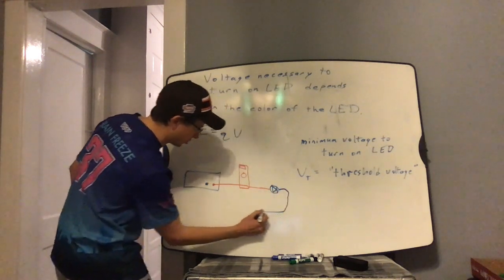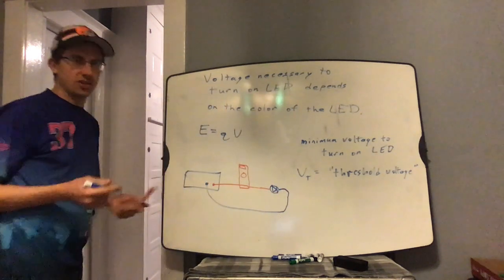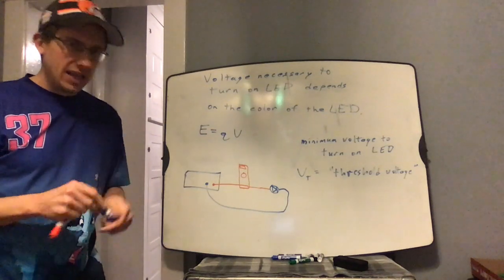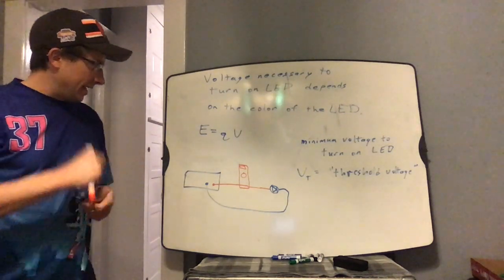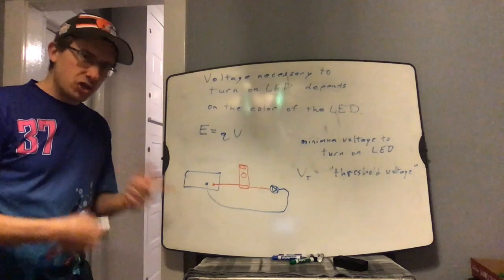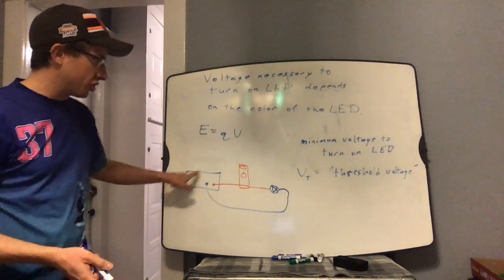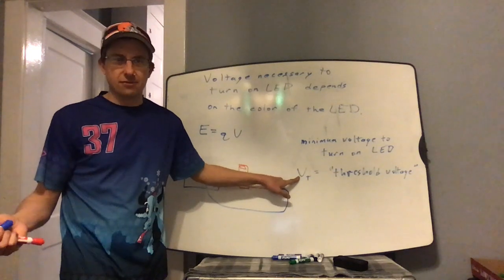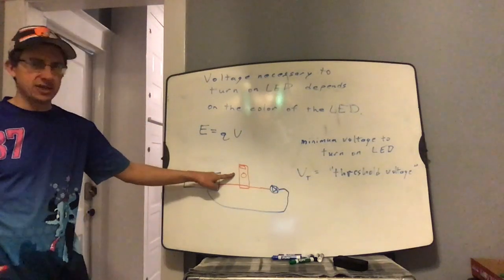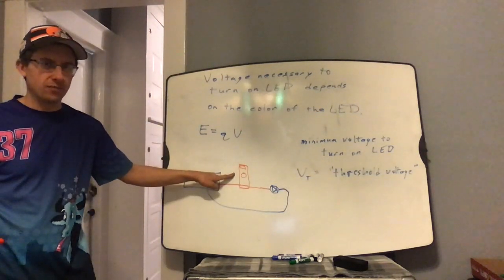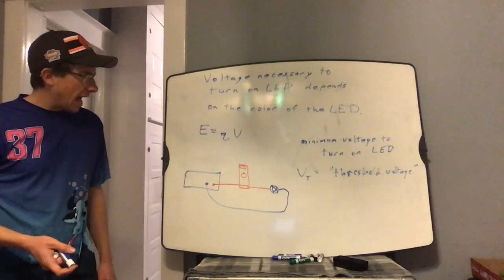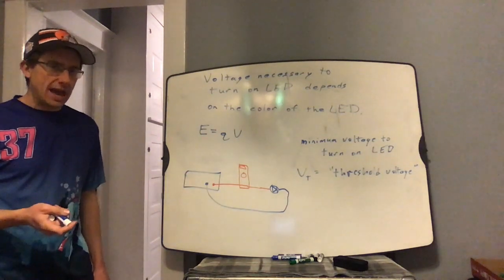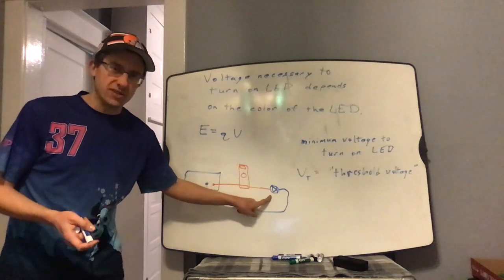And then I'm just going to send the LED back into the power amplifier. If the threshold voltage is not reached, then the LED is giving off no light. And if the LED is giving off no light, there is going to be no current in the multimeter. So I am going to measure the voltage at which the LED barely turns on.